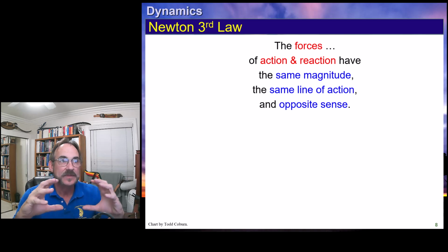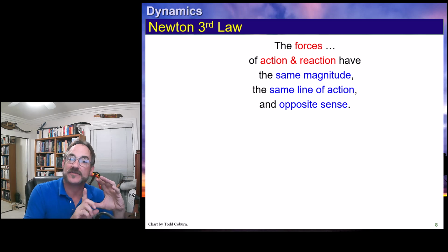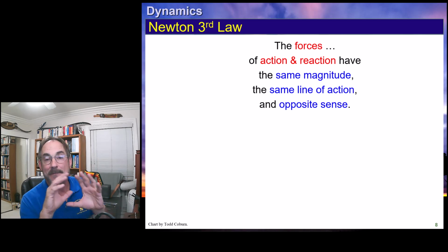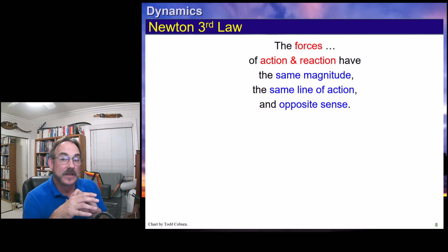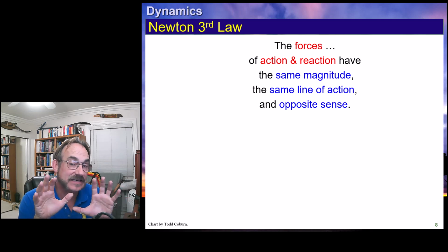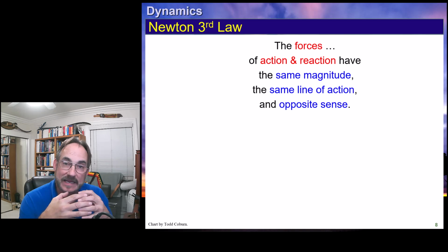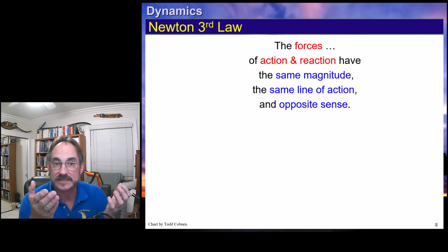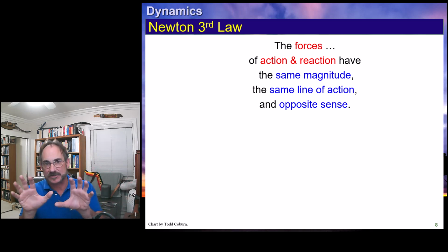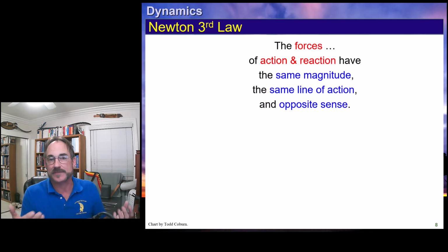He's sitting there. His action force, his weight, is acting down on the ground. The reaction of the ground is up. Okay? And these have the same magnitude. We always have to have a reaction that completely balances. If it doesn't balance, we're going to end up with some way of restoring that equilibrium, and that's what that acceleration does. That ma vector, the mass times acceleration, is a vector, is a force, and when we account for that, our sum of forces is back to zero.